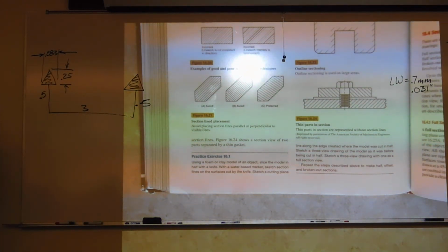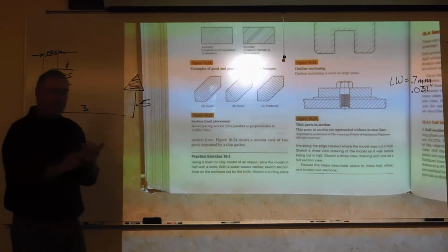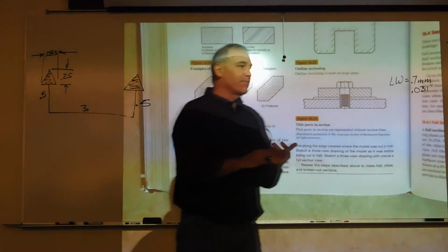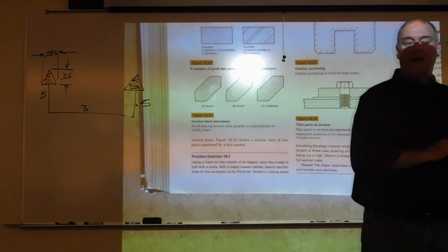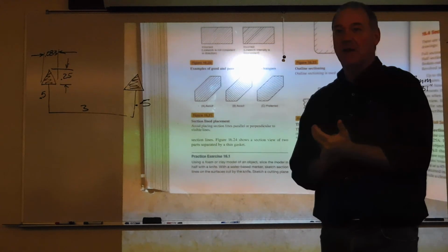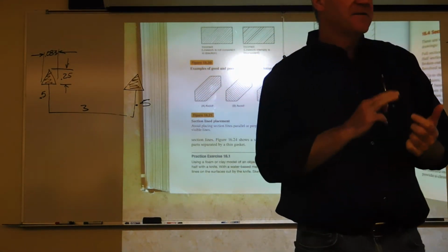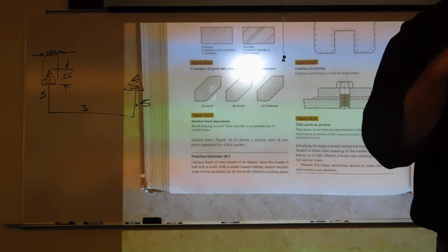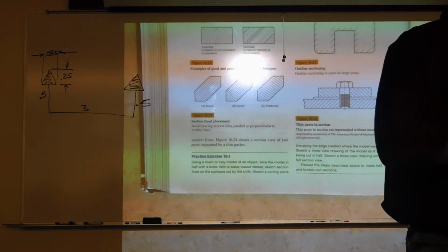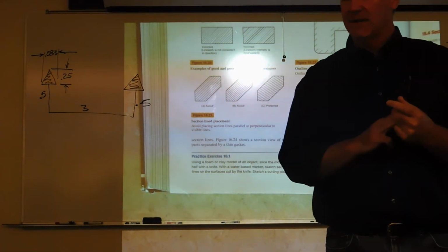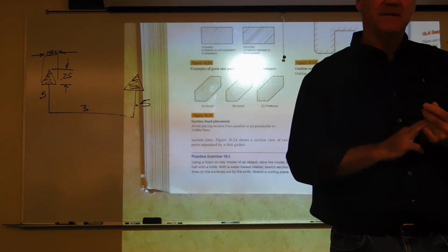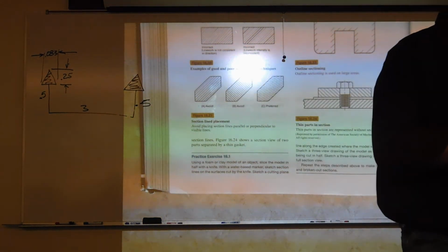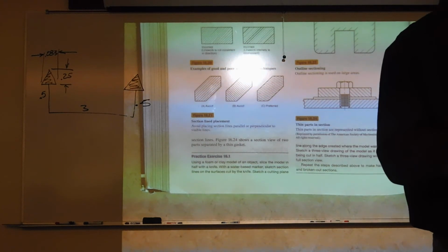All right, so when we're doing sections, you have two line types. Cutting plane line, which should have phantom line characteristic, be very thick, and have arrows at 90 degrees denoting line of sight. Cutting plane lines will be in the adjacent view. In the section view itself, you will only interject section lines. These will be thin lines in a set pattern, typically 1/8 inch apart, 45 degrees.